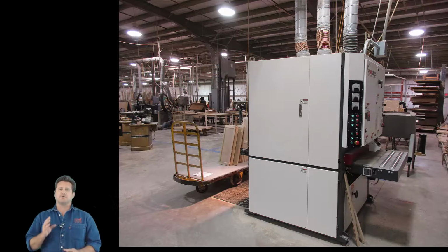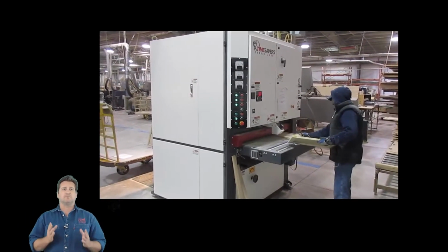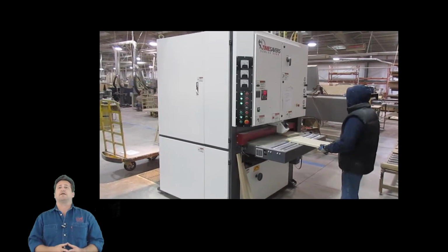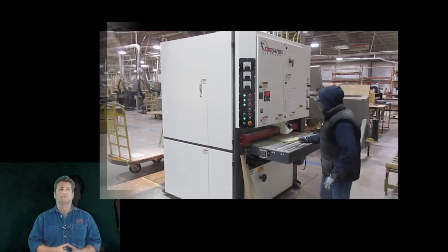After assembly, the shaker door moves through one of our triple head wide belt sanders where the door progresses through a 3-step sanding process. The first belt is 120 grit, followed by 150 grit, and then finally 180 grit. This process removes 15 thousandths from the surface and is being shown.